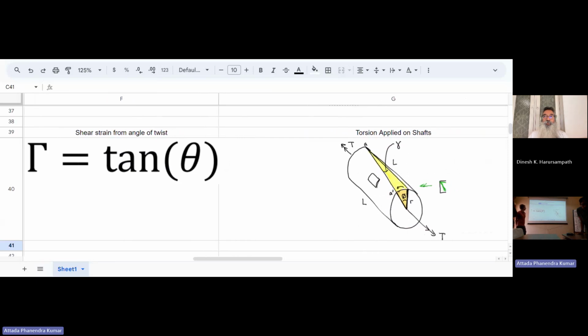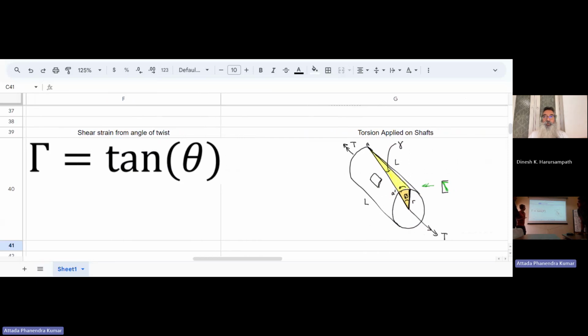So it leads to torsion. One example is applied in the shafts. You see that in this figure you have used phi for the angle, so that theta should be phi, not theta, so you don't mix up the variables, because in the polar coordinate system you have r, theta, z there. Theta becomes an independent variable, whereas phi is a dependent variable. So phi depends on x1. You have to make sure that the gamma subscript is 1 theta, but what is within the tangent is phi 1.